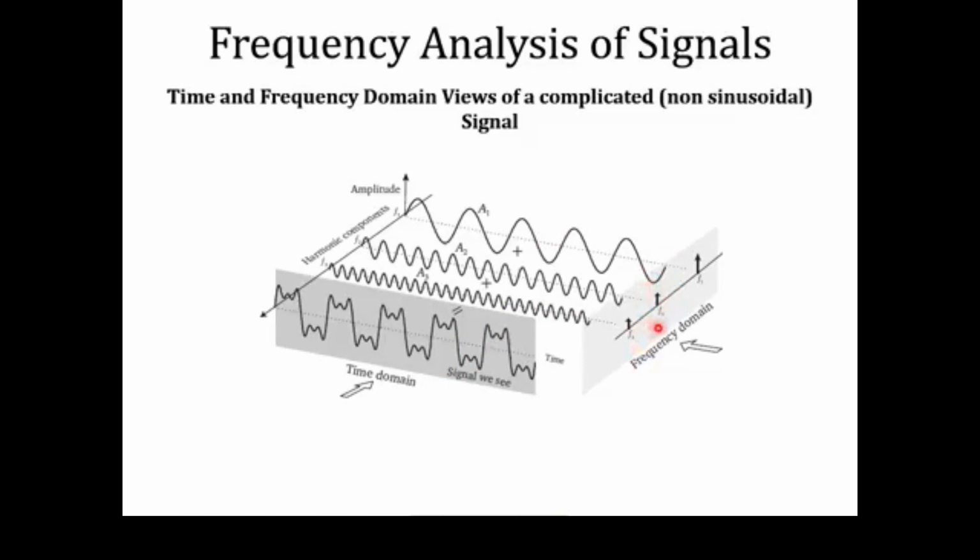So by observing the height of a spike, we can tell the strength of a second harmonic component. So by looking at signals information in frequency domain, we can easily tell the strength of each and every harmonic component. So this is the main advantage or the most important advantage of observing signal information in frequency domain. Another important advantage of frequency domain representation is the signals spectrum helps us to describe the effects of certain systems.